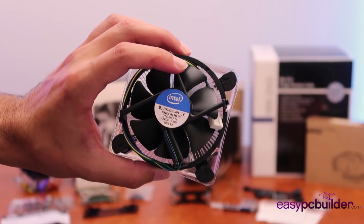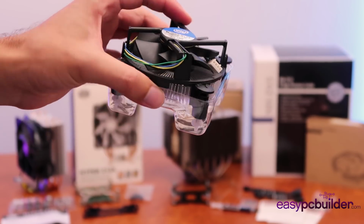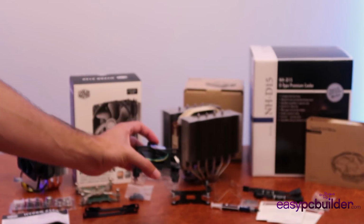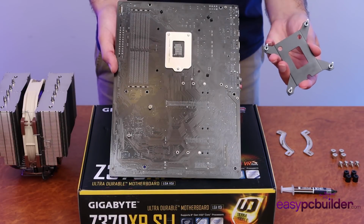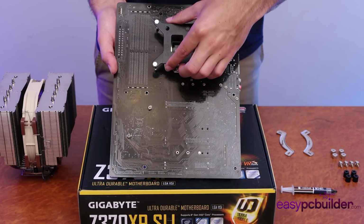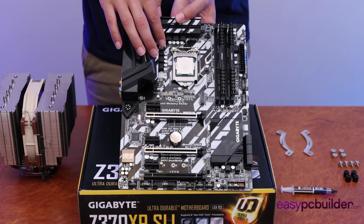A small CPU cooler with limited surface area can only increase the fan speed so much in order to control temperatures. And when the limit is reached, the CPU will begin to limit its processing and heat generated to ensure it doesn't damage itself. If you are keeping a CPU within manufacturer specifications, a stock cooler is fine, but where you tend to overclock it, increasing the speed and hence heat generated, you need to upgrade to ensure you don't hit this thermal limit. The installation of these larger coolers is usually more involved, with brackets required on both sides of the motherboard to support their weight.